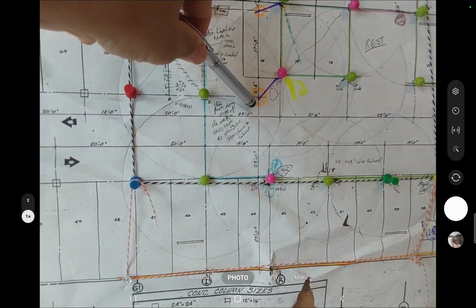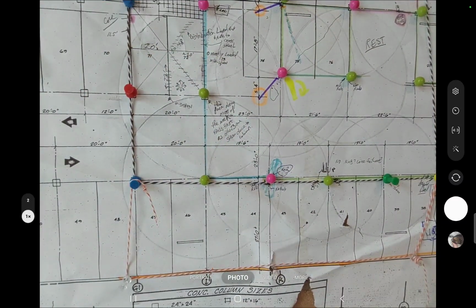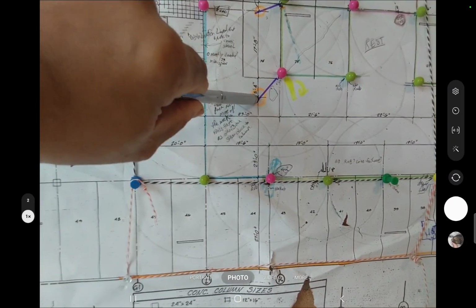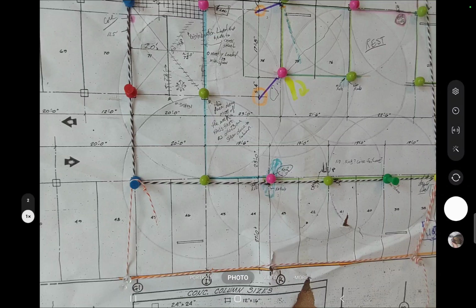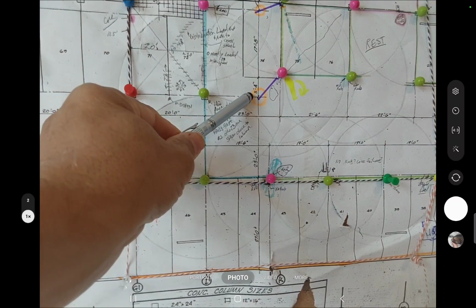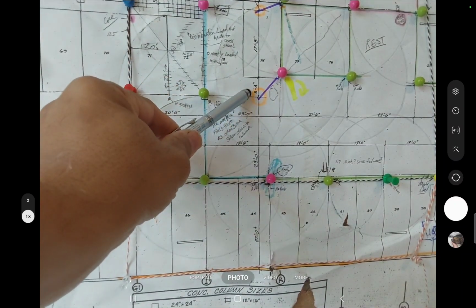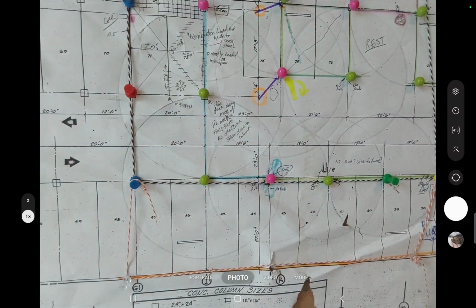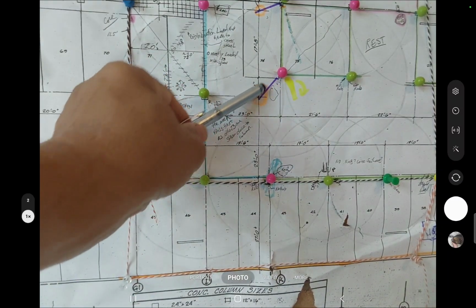We'll get to that again. That's the offset I talk about. This is not my drawing. These are the real plan drawings, the true plan drawings, supposedly. And the offset, you see 5'4" here. It's really 6 foot. I think it's 6'2" or 6'4". At this measurement they're measuring from the face instead of the center line, but in another measurement they'll go center line. So the offset is a little different here. You have to add a foot to this if you want to extrapolate more consistently with the drawings. So this is 6 foot and some change.